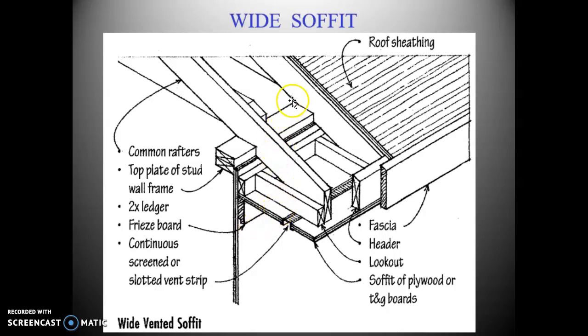But here's what happens again. Heat rises. So picture this. Hot, sunny day. You have black asphalt shingles on your roof. Your attic is heating up. Well, you have insulation in here to prevent that heat from penetrating your house. But your attic gets really hot. You have to vent your attic. Hugely important. Gigantic important.